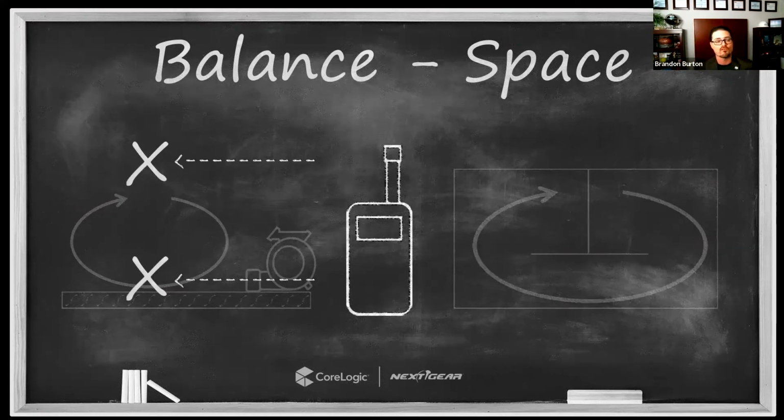Okay. In other words, I'm not concerned about a 1/10 of a degree difference or a 1/10 of a percent relative humidity difference. But if the air well above my surface is at 30% relative humidity, but the air in contact with that wet floor is at 70 or 80% relative humidity, that's a problem. The air movement has not been effectively deployed.